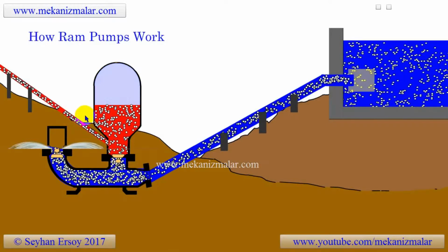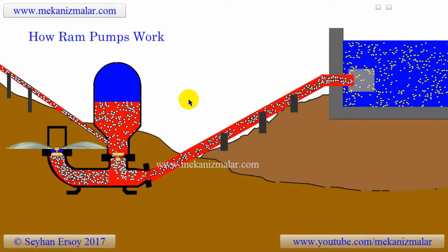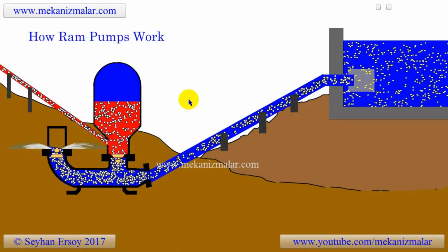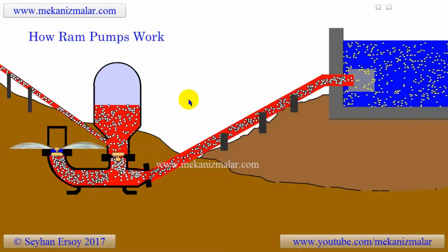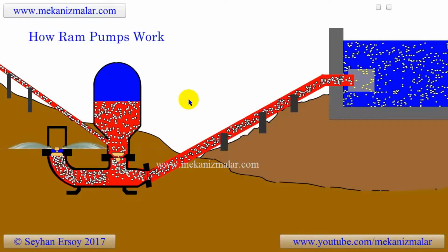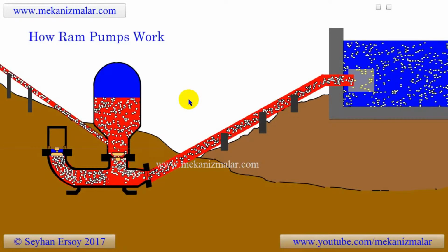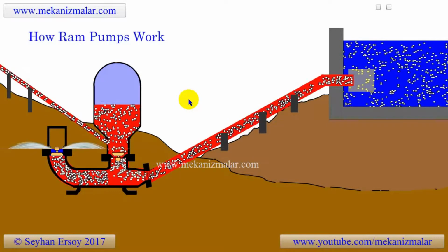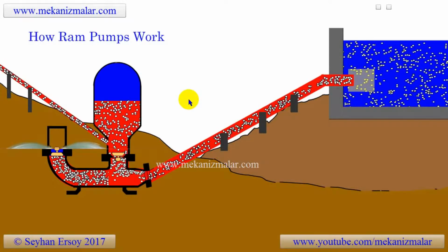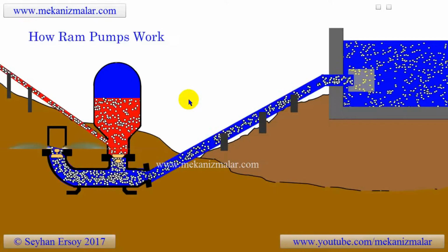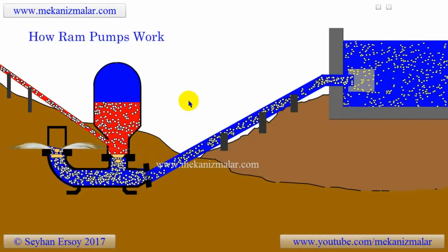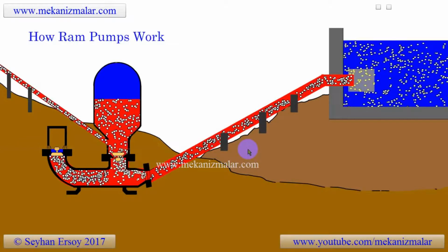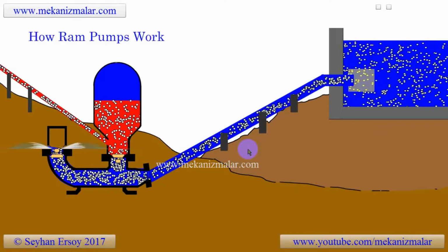The system may seem like it's disposing of too much water, but it's not the inefficiency of the ram pump, but instead the requirements of the conservation of energy principle. If 10 liters of water per second is fed to the ram pump and 2 liters of water per second is pumped to 100 meters of elevation, this would violate the conservation of energy principles. But a quarter liter per second is a darn good flow rate for the system mentioned and does not violate any energy principles.